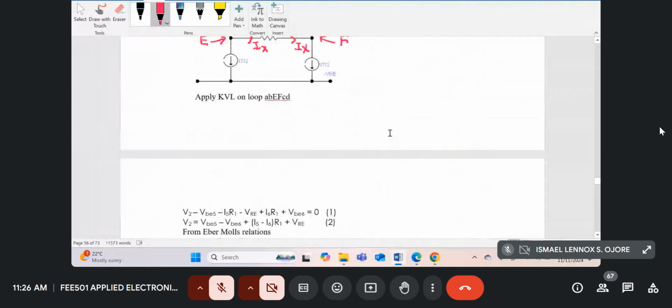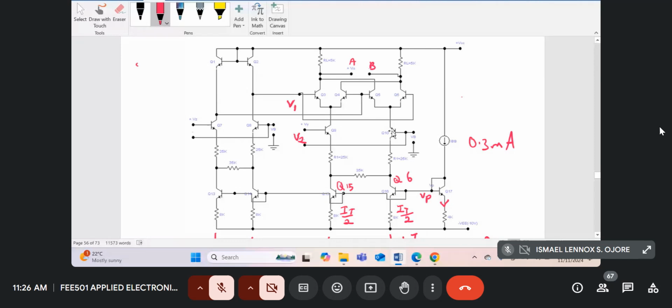All we've done from our earlier multiplier is to consider a practical multiplier. And now we've finished everything to do with the Gilbert multiplier cell and this new technique of biasing Q9 and Q10 in this circuit. So all that will remain is for us to analyze the pre-distortion circuit. We've proved that this circuit will multiply when R1 is 0. This circuit will multiply when R1 is something. The effect of R1 is just to increase the linearity at the expense of the gain of the system. So in the next class, we shall do this preconditioning circuit.